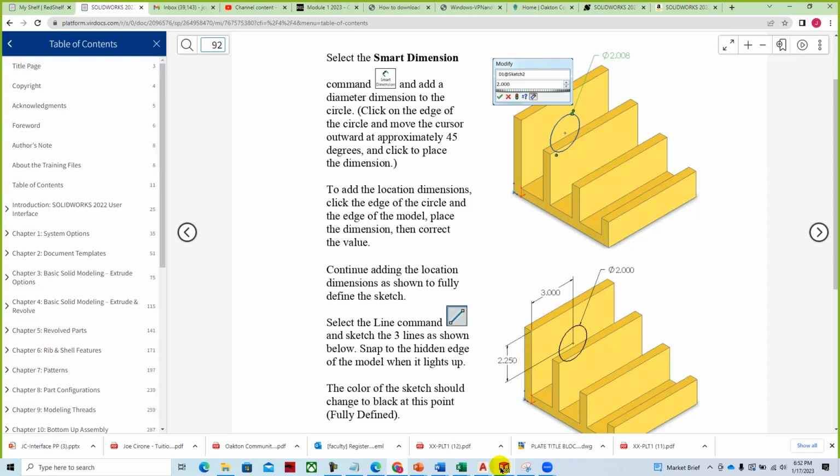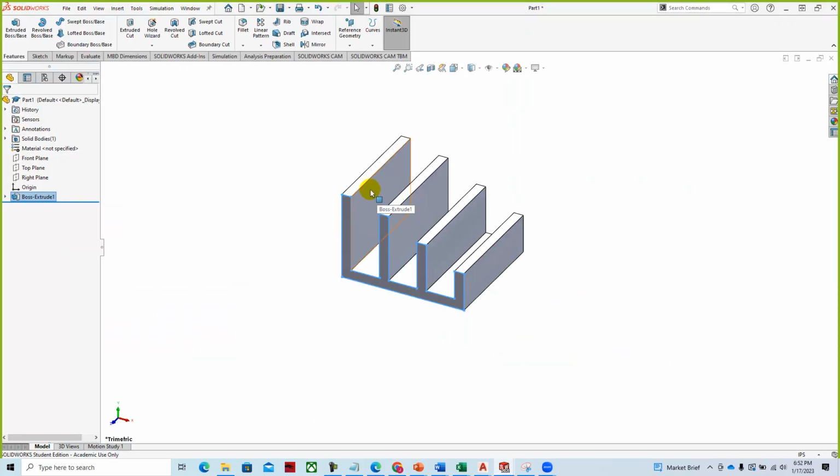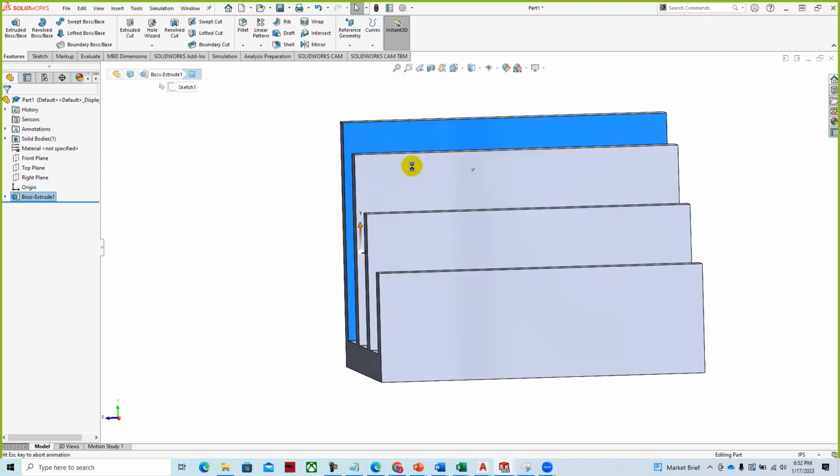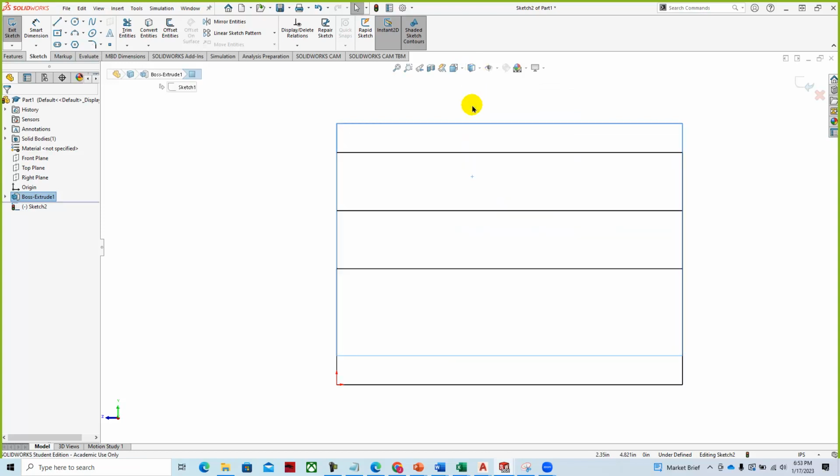we can locate that. And so if I come back here to SolidWorks and I want to sketch, what I'll do is I'll click here and I'll say start a sketch. And then it will line it up on that sketch. And we can go through and we can change the visibility so that we can actually see through the part model, show it with hidden lines if we want to. And then I can create a circle.